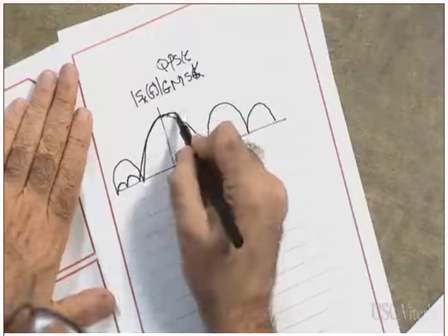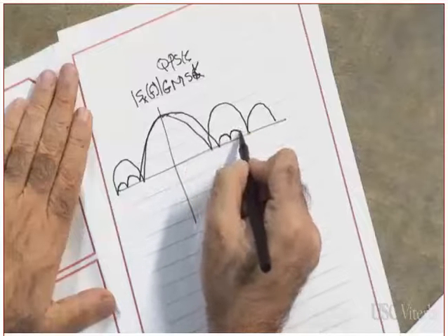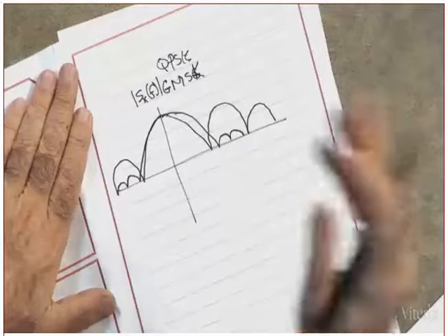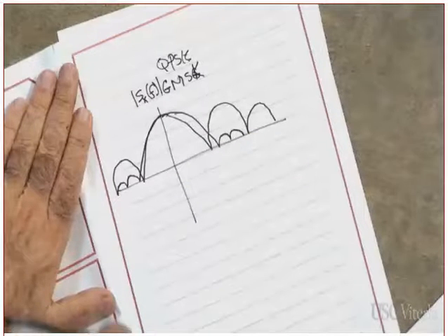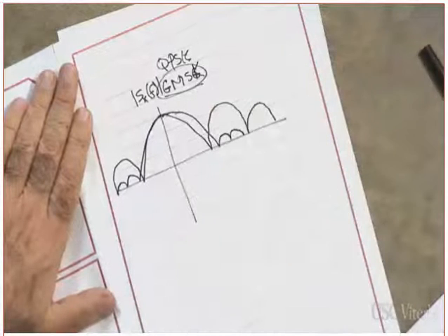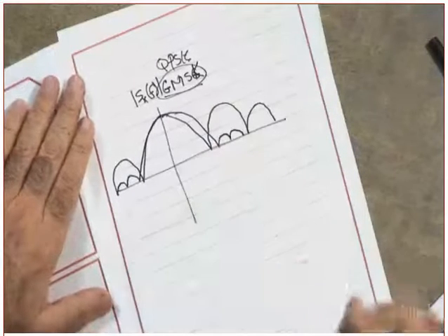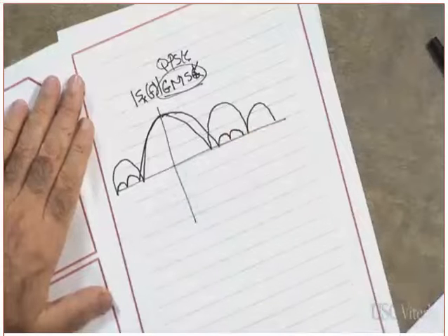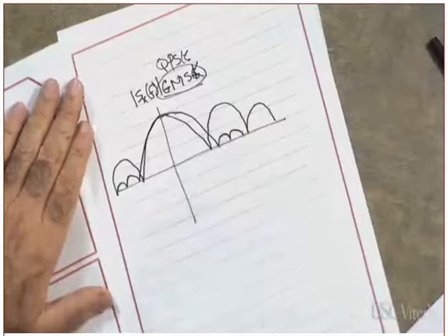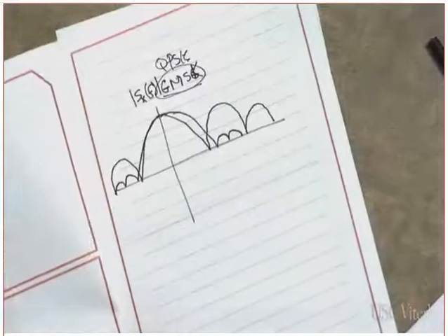Tell me what you see. The main lobe is a little bit wider, but the side lobes die faster. Why? Because these signals are constant envelope. Did you understand what I just said or not? So even though the main lobe is a little bit wider, the side lobes die quicker. Clear?